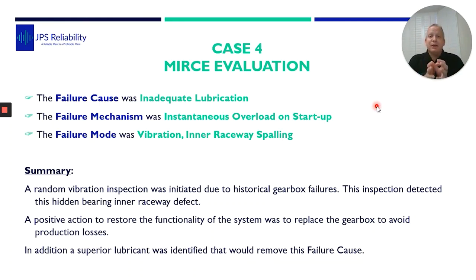The mechanism of failure is the instantaneous overload on startup with inadequate lubrication. And the failure detection mode was through vibration analysis, and there's an inner race spalling defect.